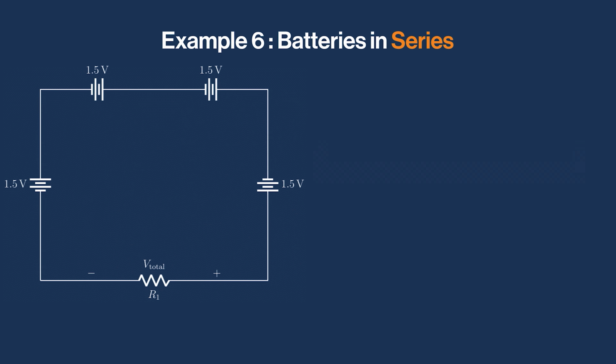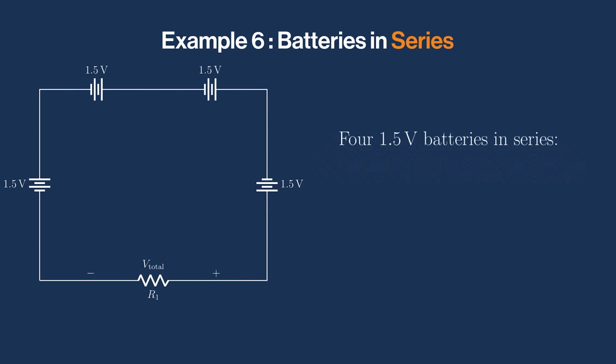Let's say you have 4 AA batteries in series with one another. This is the exact same setup in your battery pack. A AA battery has 1.5 volts. And so when you put them all in series, you get a total of 6 volts. This setup is typically used in flashlights, laptops, and RC cars. Cool, but what about batteries in parallel?